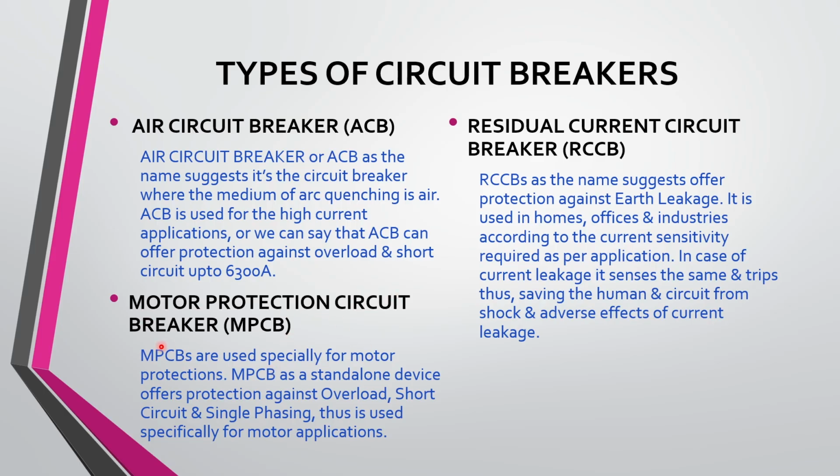Motor protection circuit breakers, MPCBs. Motor protection circuit breakers are used especially for motor protection. MPCB as a standalone device offers protection against overload, short circuit, and single phasing, and thus it is used especially for motor applications. Now coming to residual current circuit breaker, or in short RCCBs.